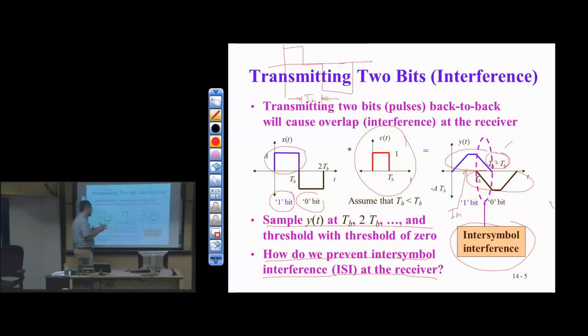Again, you need some cues from the transmitter. The transmitter has to send a PN sequence or something like it over the channel, and the receiver will then train an FIR filter typically to undo this channel distortion. An inverse filter as best it can. Undo the damage, if you will, as best it can. It won't be a perfect undoing of the damage or compensation.